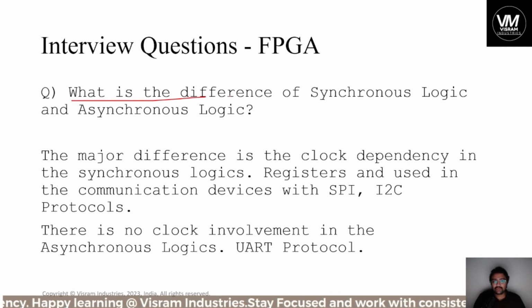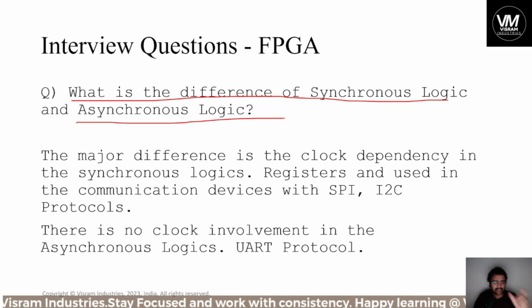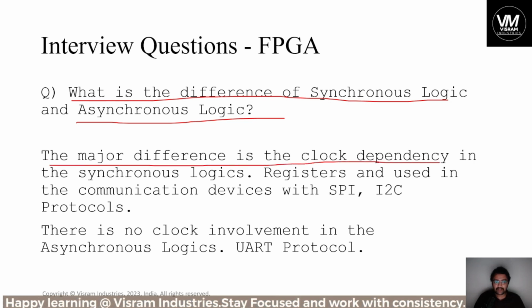So the next question is, what is the difference between synchronous logic and asynchronous logic? Okay, the major difference is that synchronous has a clock. Every process, every data transmission, everything happens at a certain particular point of time with respect to the clock. But asynchronous is not dependent on the clock. Let us see how you can give this answer. The major difference is the clock dependency.